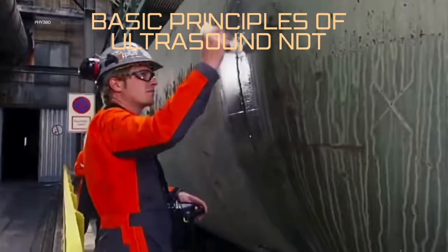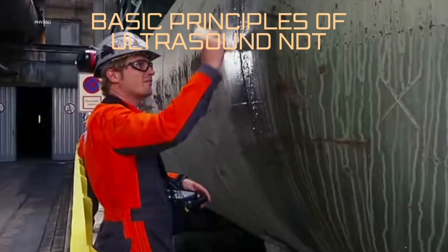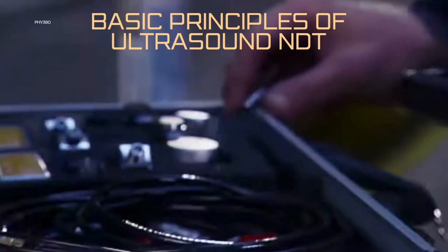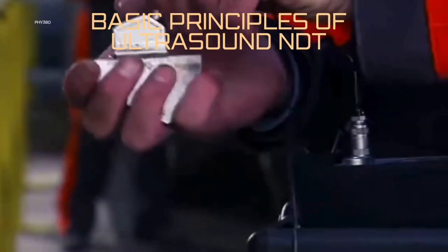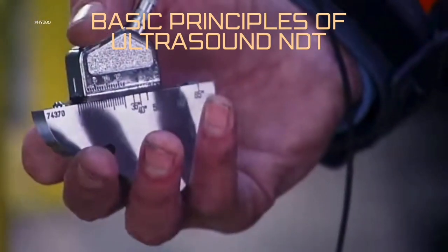The examiner first applies a contact fluid to enable the ultrasonic feeler to make proper contact with the material. This bonding layer serves to conduct the sound waves into the material. Without the contact fluid, they would immediately bounce back from the surface. A transducer converts an electronic signal into ultrasonic sound waves. It can both send and receive.